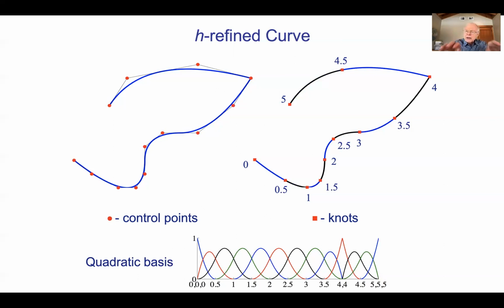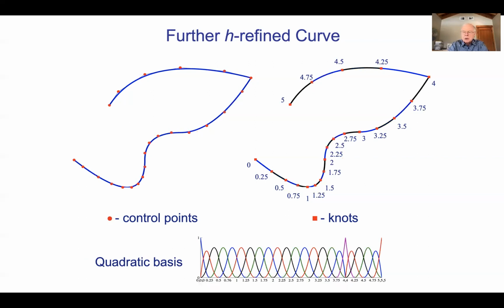This is unlike finite element analysis. In finite element analysis, you have to find the geometry. The geometry is a separate entity from the mesh. The mesh is an approximation. So you can't just refine the mesh without looking for the geometry to know where the other points should be. So again, we now have a finer mesh with the same geometric object. The geometric mapping has been fixed, and we can get a more accurate result if we were to do analysis. And we can go on and do that again and again, as you can see here.